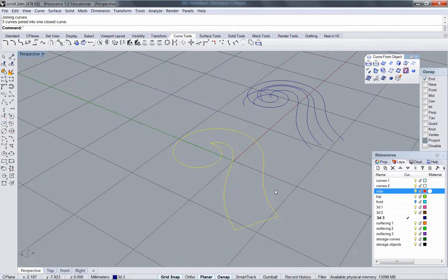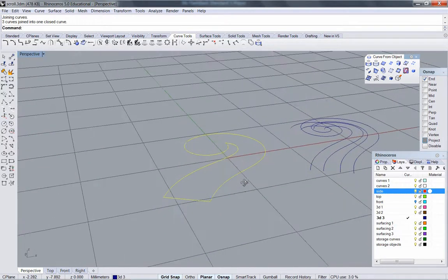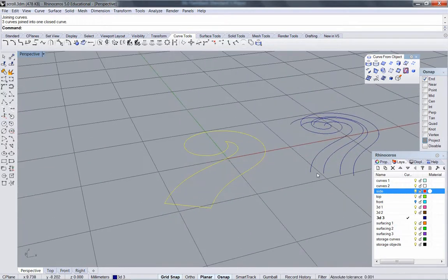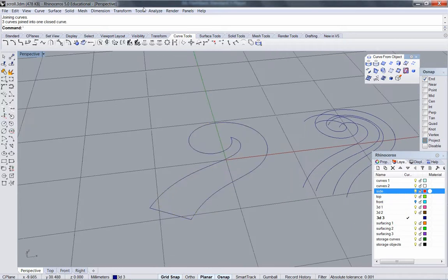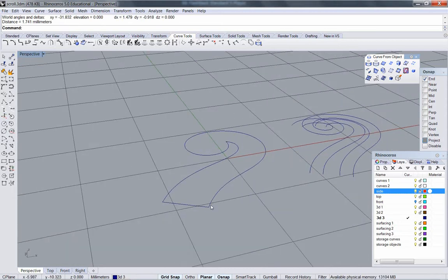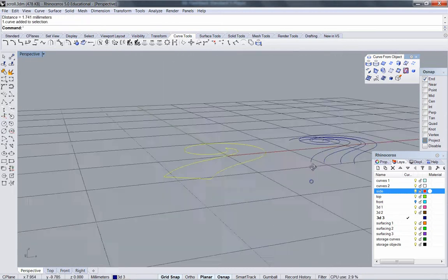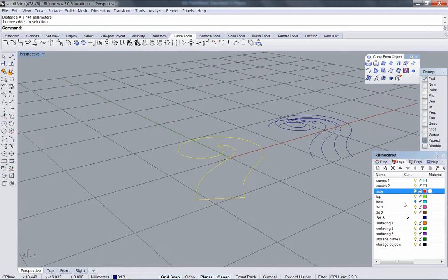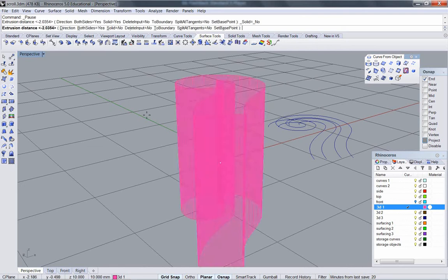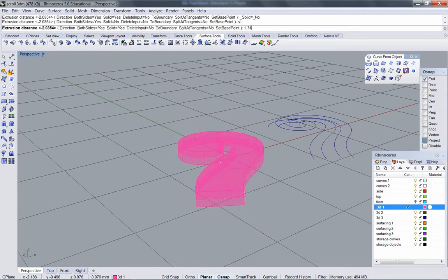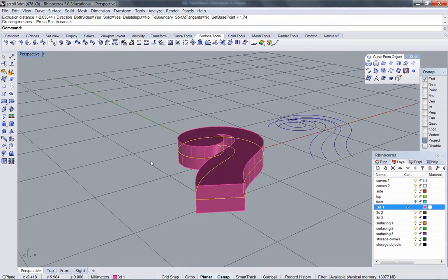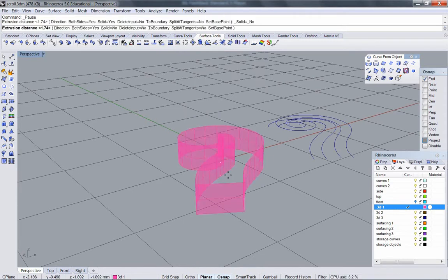My question is going to be how thick do I want to extrude? If I'm going to use a fillet this distance, okay? Analyze distance, see what that is. It's 1.74. The thickness of my piece has to at least be that thick so that when the fillet happens, okay, I didn't want that both sides.